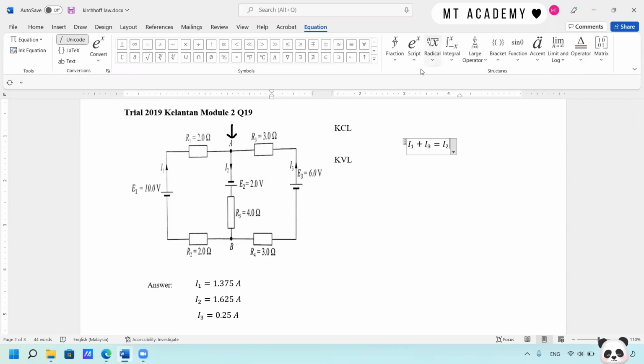And then we're going to apply the Kirchhoff voltage law. Here I would suggest clockwise direction because it flows out from the positive terminal of the 10 volt, which is also flowing out from the positive terminal of the 2 volt. So here we have positive 10 plus 2 volt equals the voltage across R1, which is I1. And also here we have another I1. You can see I1 is flowing in this direction.